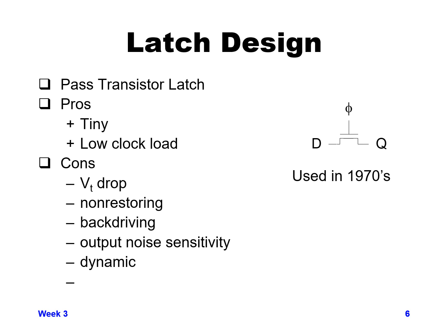It's dynamic in that the values can change when you're not driving it, and you have a diffusion as your input, and so instead of going just to a gate, going to a diffusion, you get more potential parasitic current going through, which can cause problems for the amount of load on your previous stage. So going to a gate of a transistor, you have no current draw. Going to the drain, you can get some current draw even when you turn that transistor off.